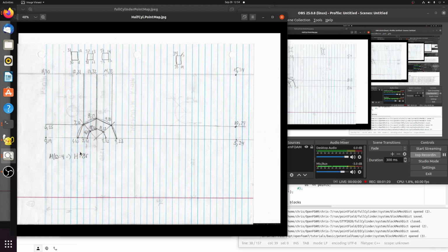So we're going to have to build those up, and we're going to have to specify the block meshes and the arcs properly. But really, the arcs we can just copy and paste, because the x-axis is the same, the z-axis is the same. The only thing that's going to change is the y-axis. So we can copy and paste and then make the y-axis negative all throughout, and that'll give us the same points. So it's not a lot of points to enter in or mathematics to do.